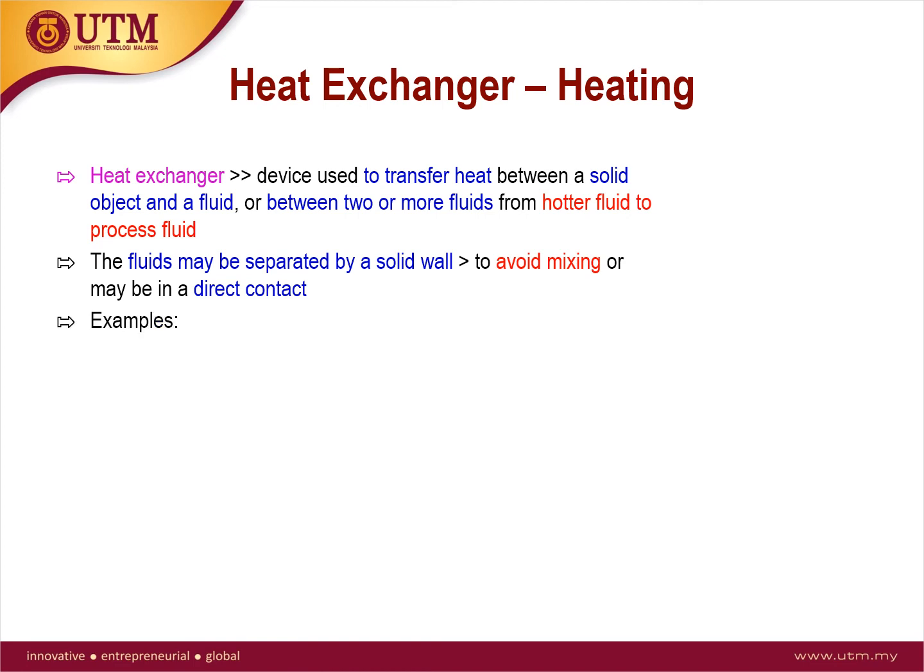For example, the most commonly used heat exchanger in industry is known as the shell and tube heat exchanger. A shell and tube heat exchanger consists of a series of tubes which contain fluid that must be either heated or cooled. A second fluid runs over the tubes being heated or cooled so that it can either provide the heat or absorb the heat required. A set of tubes is called the tube bundle and can be made up of several types of tubes, which are plain, longitudinally finned, and others.